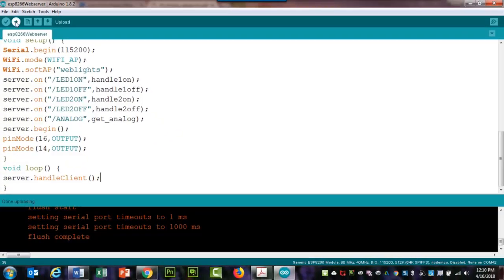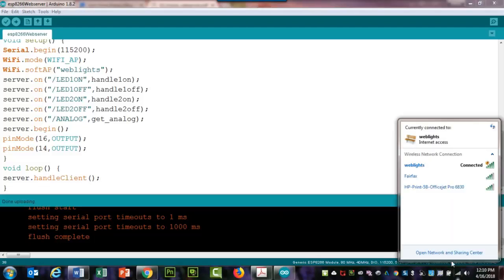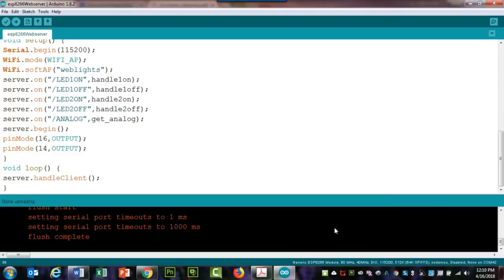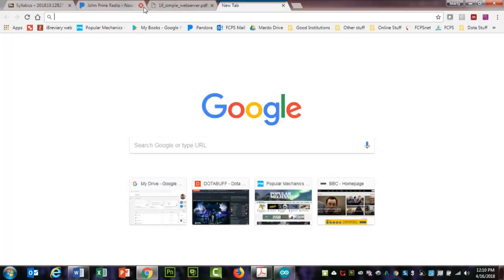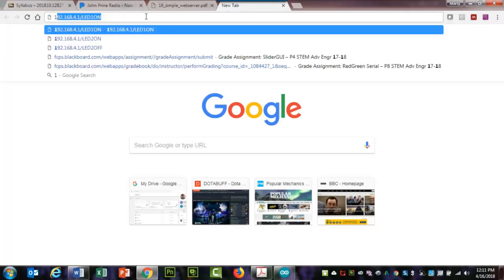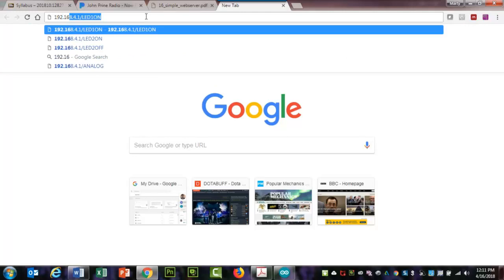So you upload this, and when you upload, you should see WebLights come in. I've already connected to WebLights, so I'm good to go. Now it's just a question of going to a website. I've got my browser on, and I'm going to simply type 192.168.4.1, which is my server address.